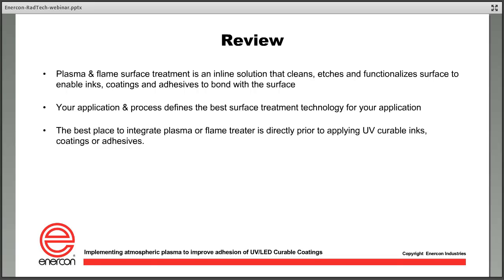Your process and your application are going to demand what route we go. There's not necessarily one set path for each application out there, and we understand everyone's needs are a little different. And really the best place to integrate a flame or plasma piece of equipment is directly before you apply the ink, coating, or adhesive and cure it. So in a perfect world, that's where we'd like to see that happen.